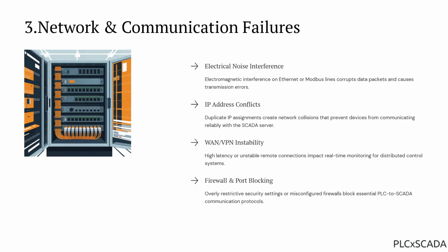Next one is firewall and port blocking. If the user misconfigures the firewall, it may block the PLC and SCADA communication. In a lot of industries, the IT department may install a lot of software to block external or internal communication. So this may block the PLC and SCADA communication.